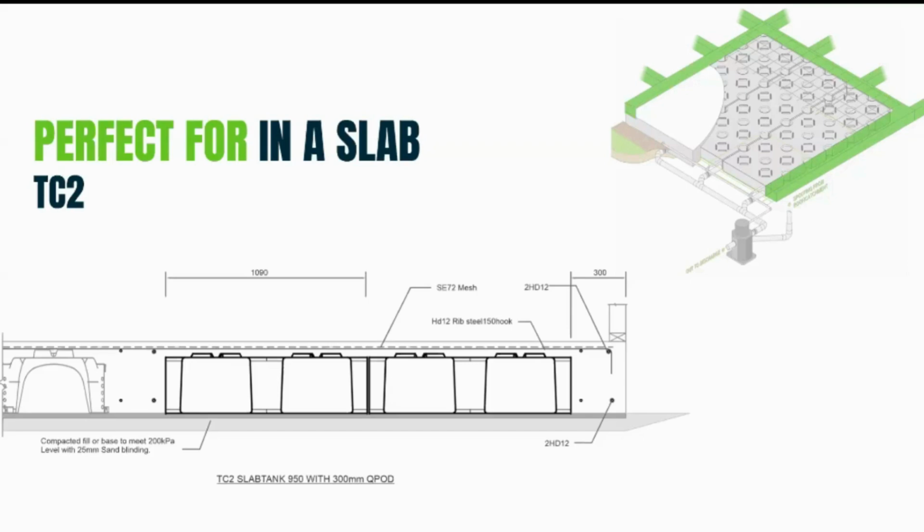Just another question as well. Could the system be adapted to provide flood volume storage? Certainly. I mean, these are designed to carry water. Just the caution on where you're picking up that flood water from. If you're picking it up off the drive, you could be involving a fair bit of silt in that catchment. So hence the distribution chamber would catch a lot of that. But yeah, you would tend to run the risk of blocking them up more doing so.